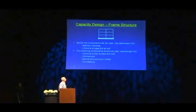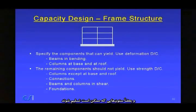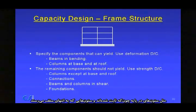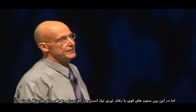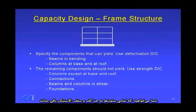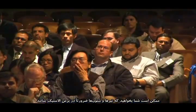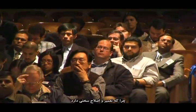For a frame structure, typically what you would do is specify that the beams can be inelastic in bending, and maybe the columns can yield at the base because it's hard to stop them, and at the roof where you've got two beams in one column, maybe the column can yield there also. But in between, you'd want strong column, weak beam behavior because this is basically desirable. And so you'd want the columns, except at the base and the roof, to remain elastic. You might want the connections to remain elastic. You might want beams and columns to remain essentially elastic in shear. And you might want no damage in the foundations because that can be difficult to repair.